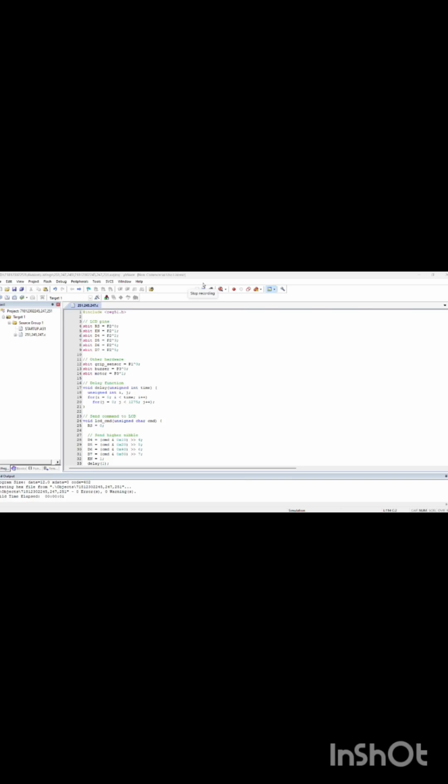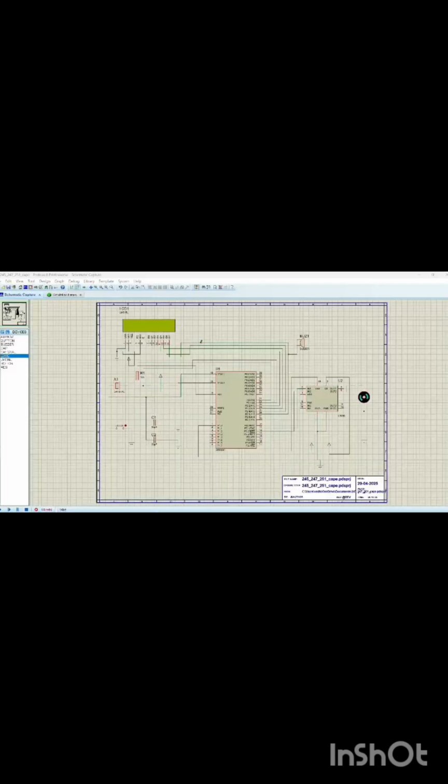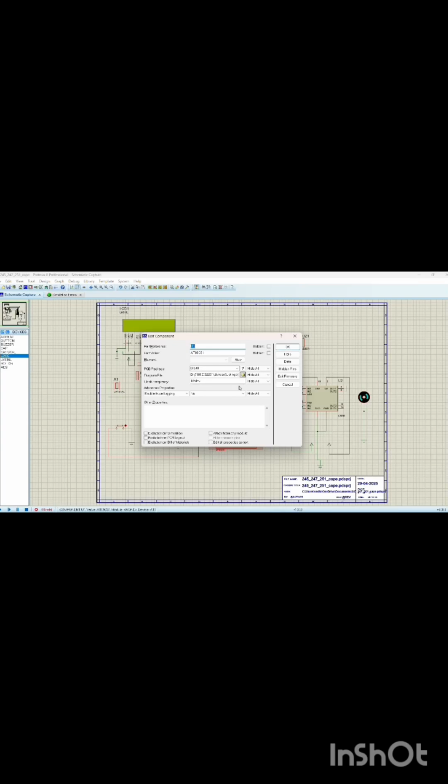In our proposed solution system, we are using an IR sensor to detect the presence or absence of a driver's hand on the steering wheel, which indicates the attentiveness. If no hand movement or grip is detected for a few seconds, the system assumes that the driver is drowsy and triggers a buzzer. Simultaneously, if the steering is moved, the system detects the direction and automatically turns the vehicle using the DC motors. In this system, no cameras are used, which reduces the cost and complexity. Fast response using real-time IR sensing, and also simple integration into low-end or two-wheeler vehicles, which provides a cost-efficient safety mechanism for a wide range of vehicles.